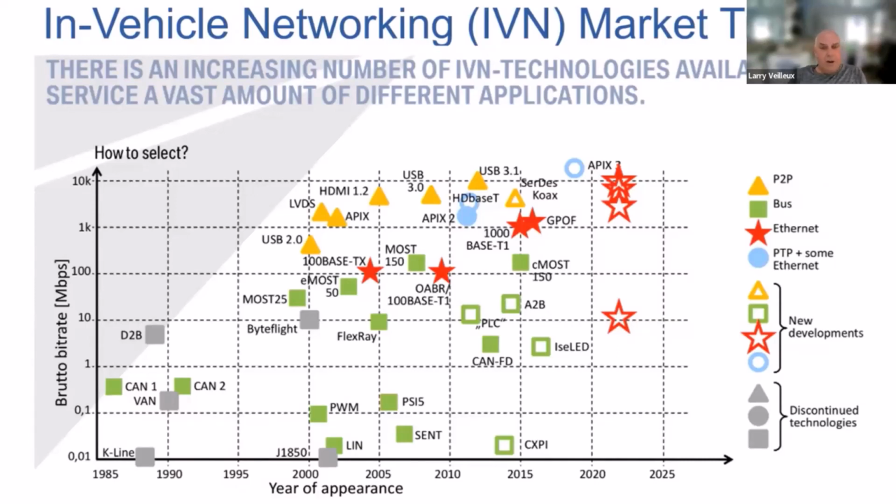That was okay until cars started becoming more sophisticated and getting more features. So the first response to that was CAN, but there have been other responses to it, and there are reasons why. I'm not going to go through every one of these here. For instance, multimedia systems take a lot more bandwidth, so that's where the MOST protocol came in. And certain systems require more security inherently, so they might be put on systems using FlexRay networking. And even CAN has evolved to its current form, which is CAN FD, CAN Flexible Data Rate.